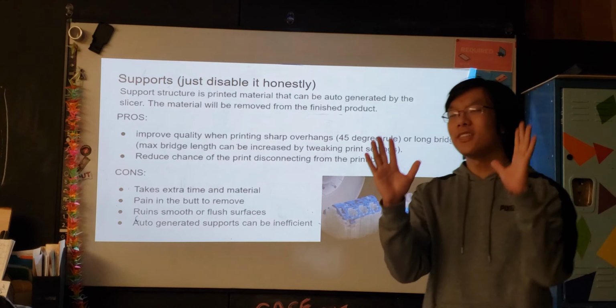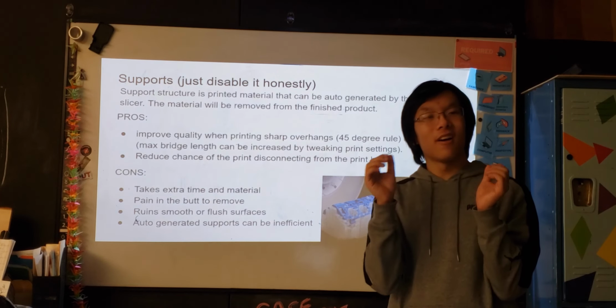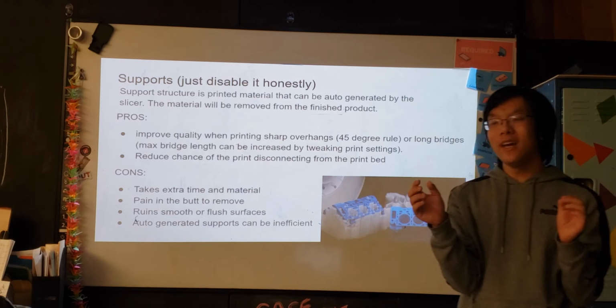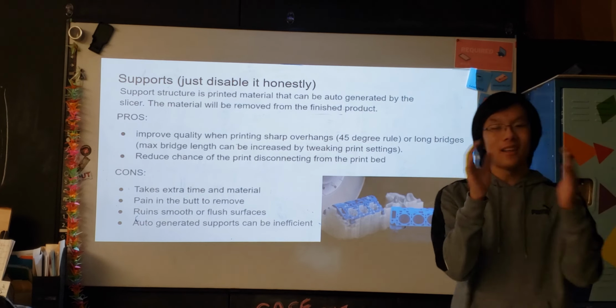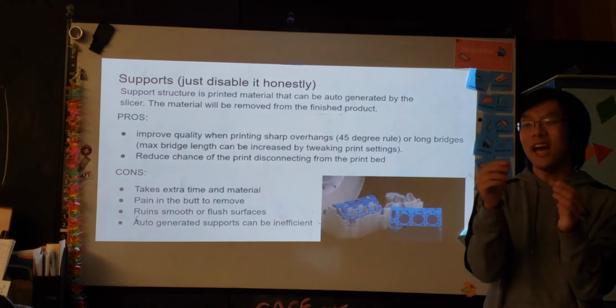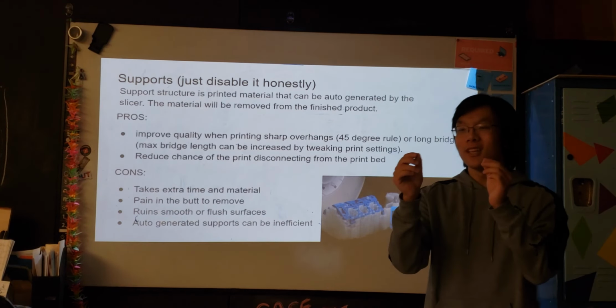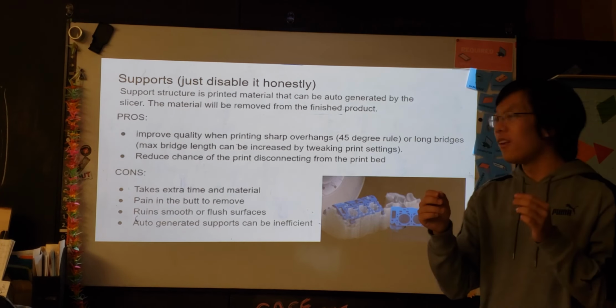Say you have a circle with a diameter of 3 millimeters, and you want to fit it into another thing that's also a diameter of 3 millimeters. You actually need to change one of the circles to be 2.99 millimeters or 2.9 millimeters.